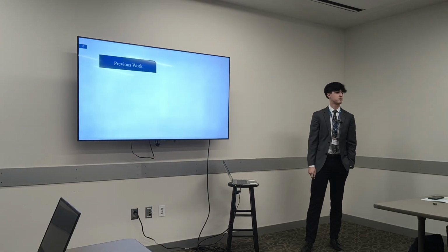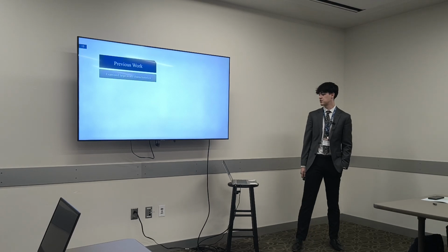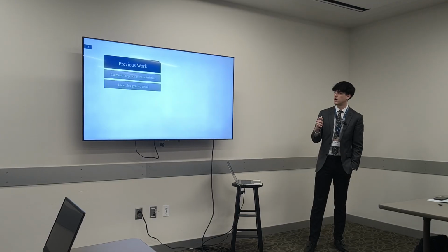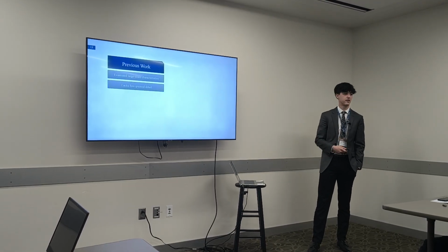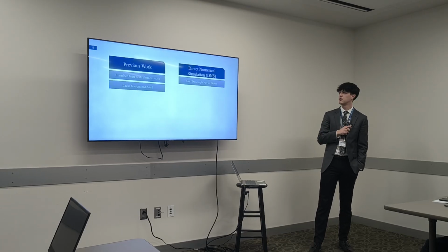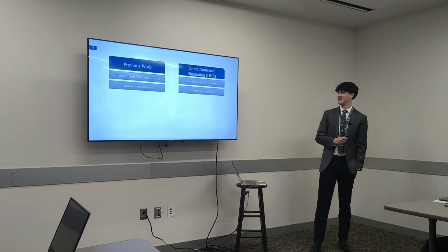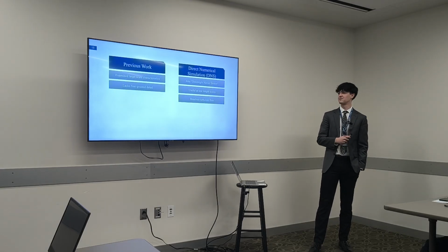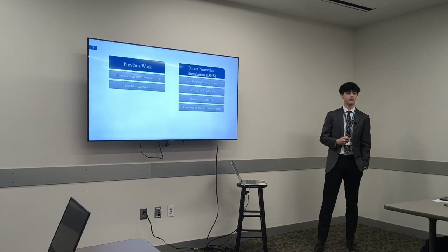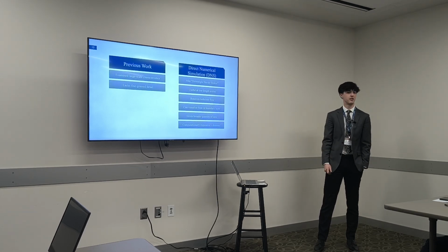And so here I'm going to be going over some of our previous work. First, we've examined some large-scale characteristics of this flow separation, but it lacks fine-grained detail purposefully, as I'll elaborate on in a future slide. So we've decided to be using another method with direct numerical simulation, also known as direct Navier-Stokes, which is useful at low length scales. It resolves turbulent flow and it can visualize flow in a boundary layer. And it also gives us a broader quantity of data, but it is very computationally expensive.